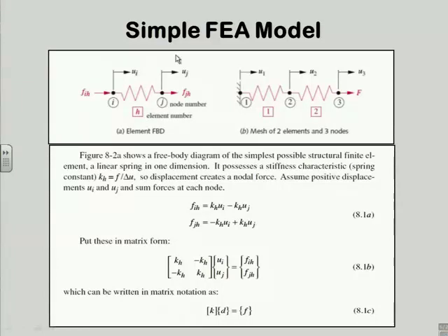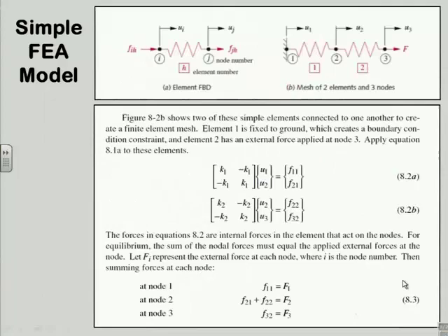And so it's simply an exercise in writing the equations associated with the sum of the forces. And there's no sum of the moments here because we have a one-dimensional system. So for the sum of the forces on this thing, we have two equations, one for the left end, one for the right end, and we can put those in matrix form, which in compact matrix notation looks like this. We have what's called a stiffness matrix with the k's. That would be the k of the spring. And we have a displacement vector here and a force vector, and that's the whole story.